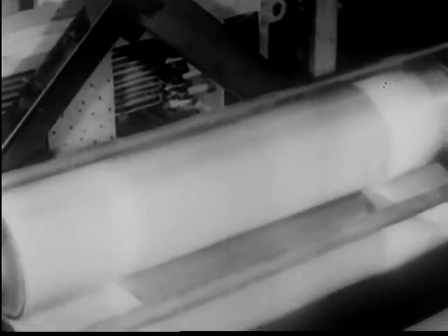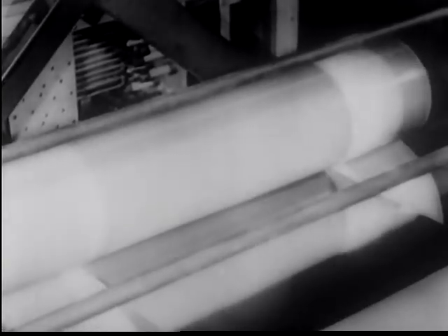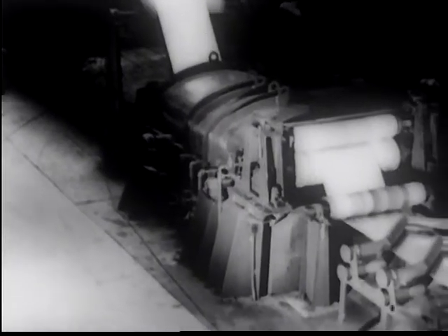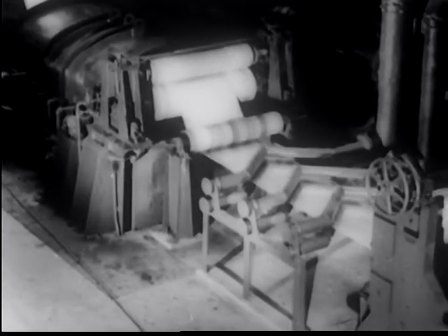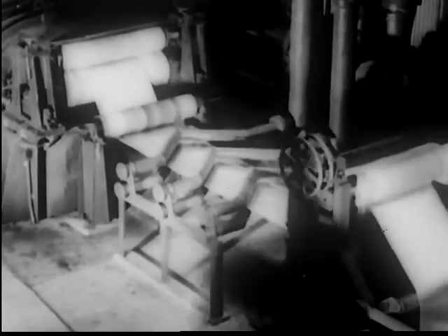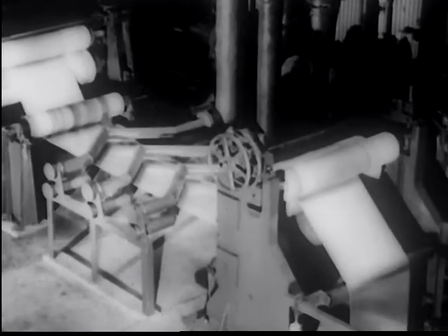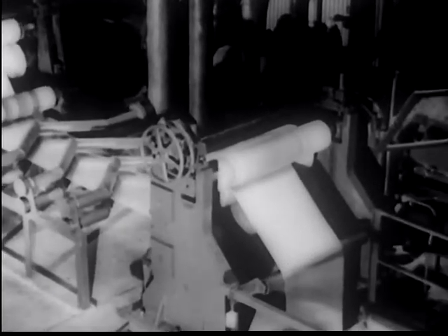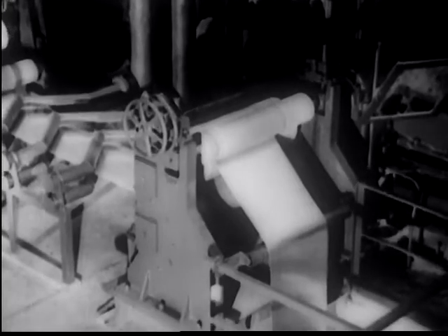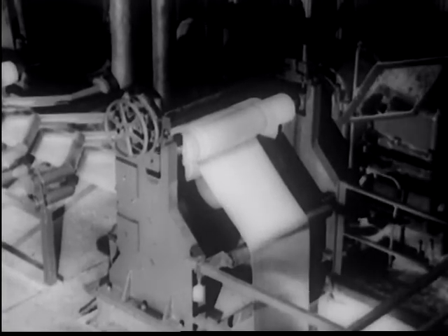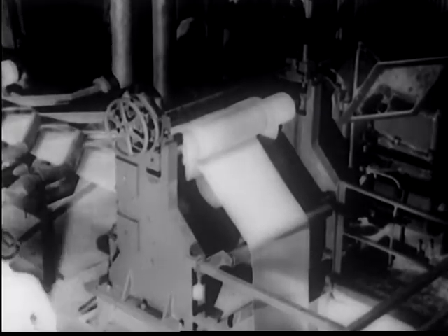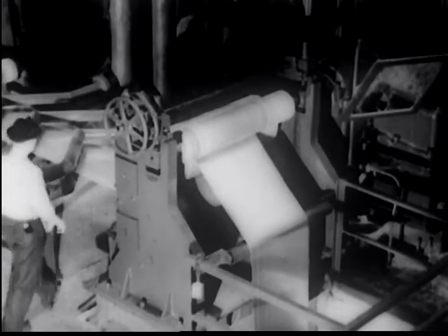Here is a new, less familiar application of electronic high-frequency generation. High-frequency heating of 200,000 cycles per second is now used to flow tin as the final step in the electrolytic plating of steel strip. After steel strip comes from its electrolytic tin plating bath, it first passes through a washer, then between hot air drying jets. At this point, the steel strip has a coating of tin that is relatively dull and porous.